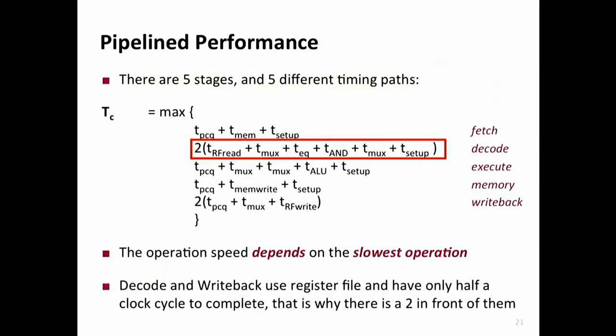The second thing that we've done over here is this assumption that we had. You write to the register file in the first half of the clock cycle, which means that you really don't do anything in the decode stage during that first half of the clock cycle, because you need those register values. It's really a forwarding path. And then in the second half of the clock cycle, you read from the register file and do everything else that's needed with those registers. Now that extends your clock cycle, because you're really trying to do 2 things in one clock cycle, writing and reading. Maybe there's a better way of handling that, right?